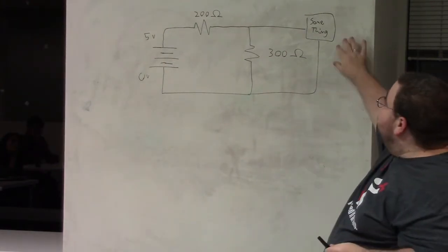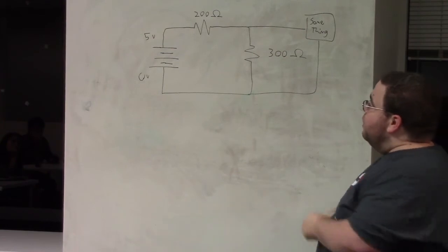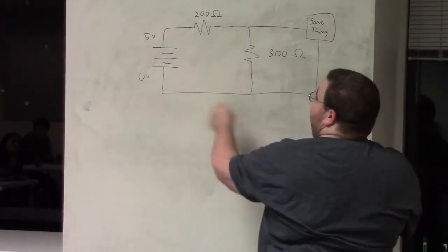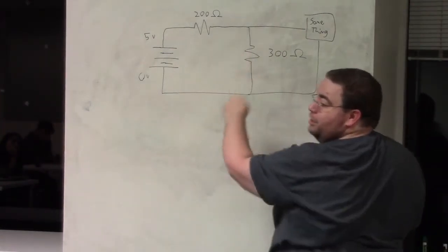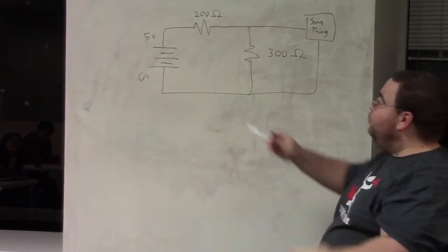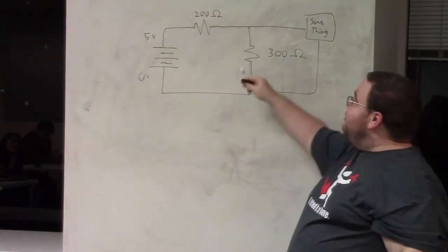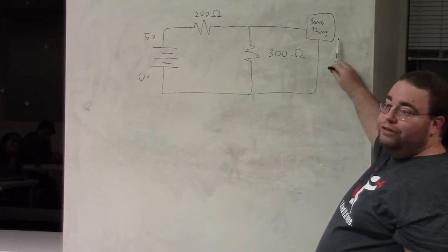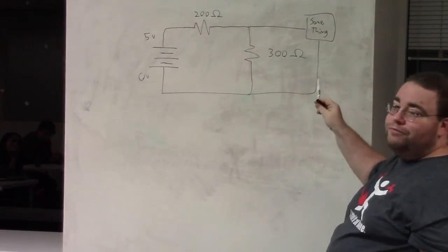Typically you wouldn't do this for other reasons, because you're wasting amperage the entire time just running this voltage divider, in addition to whatever load this thing is. But that's one way to do it.